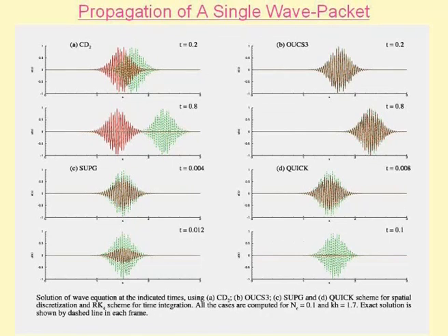Now, for the same problem though, if I use this finite volume, this is the finite element method, streamwise upwind Petrov-Galerkin method, SUPG, and look at the solution that is shown. It is 0.004 and 0.012, and you can see the green signal and the red signal. The times are so low that you do not even see their convection, right, but you can certainly see the effect of numerical dissipation. See, the solution is virtually diminishing there.